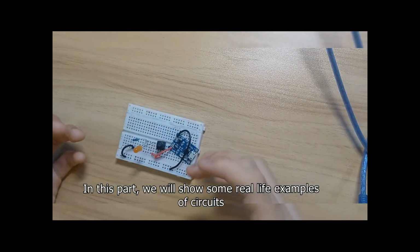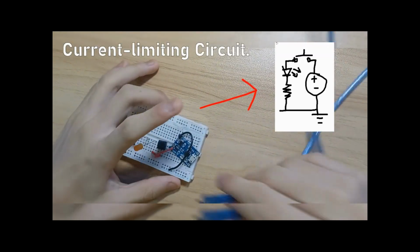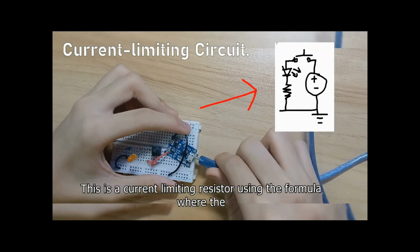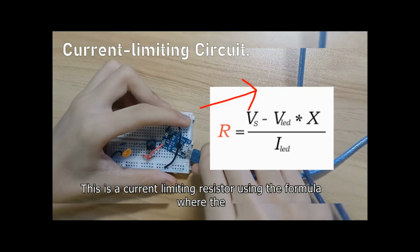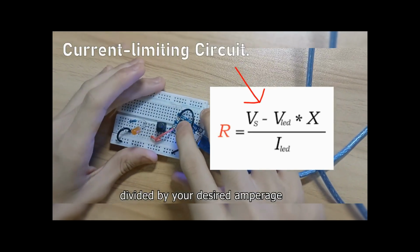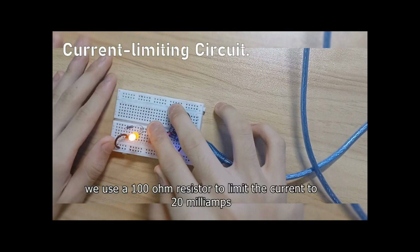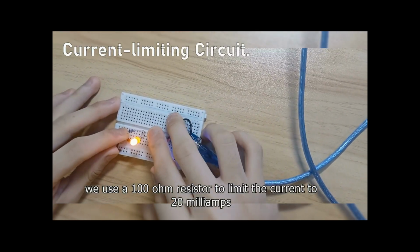In this part, we will show some real-life examples of circuits. This is a current limiting circuit. This is a current limiting resistor using the formula where the resistance is equal to the difference in supply and required voltage divided by your desired amperage. In this case, we use a 100 ohm resistor to limit the current to 20 milliamps.